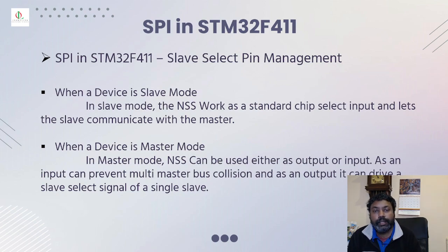Now let's see briefly or elaborately the SPI in STM32F411. STM32F411 slave select pin management. When you want the device to act in slave mode, remember the NSS works as a standard chip select input and lets the slave communicate with the master.